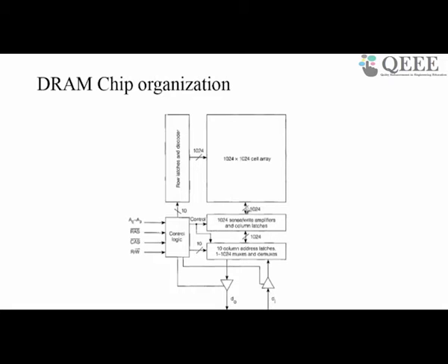Using this bus of 1024 bits, the 1024 bits corresponding to a given row will be available here, and here we have an array of sense and write amplifiers, 1024 such amplifiers. Each one of them will sense the bit that comes out in that column, amplify it, and write it back into the same cell. So using this mechanism, a row can be selected, and the entire row will be read and written back.